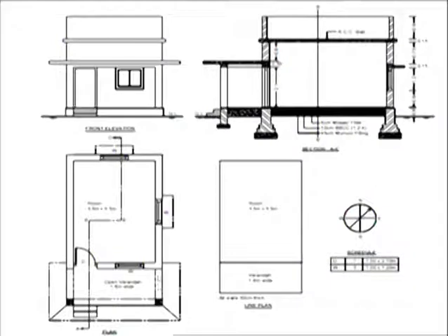Beyond the plinth we discontinue the construction of this wall, which we may call a dwarf wall or low height wall. The purpose of this wall is to confine the soil so that the flooring can be laid.